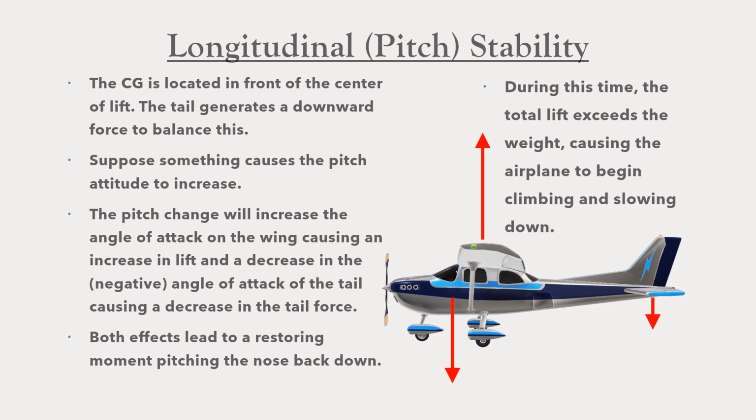Now, during the time that the aircraft is recovering back to its original pitch attitude, the lift on the wing is going to exceed the weight of the airplane. The forces will not be balanced during that time. So during that time, you will get a change in direction of motion where the airplane starts to climb. And once it starts to climb, it tends to start slowing down.